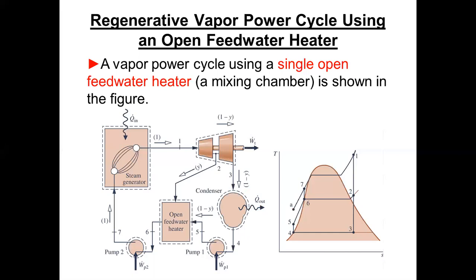Once you get it out of there, even if you have additional feed water heaters, all of the feed water is enclosed in pipe. And so then you can just come up to as high pressure as you need, so long as the pipe's strong enough to hold it, to force it into the steam generator to get you the pressure that you need entering the steam generator to make the boiler work, okay?